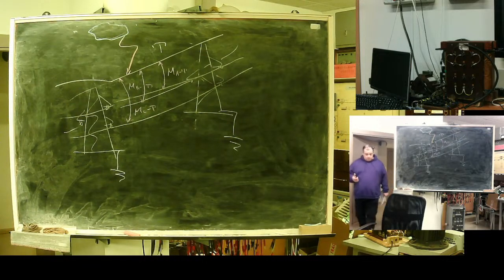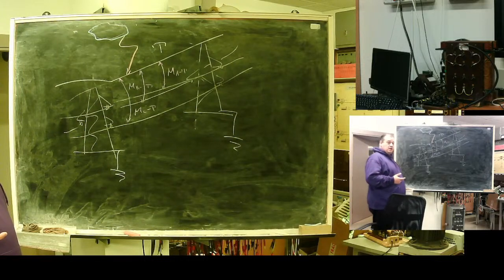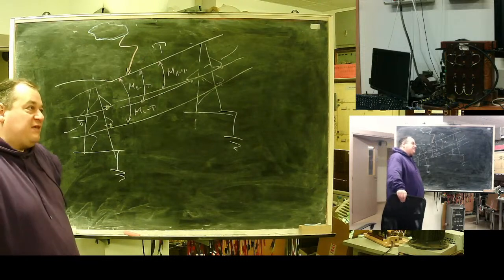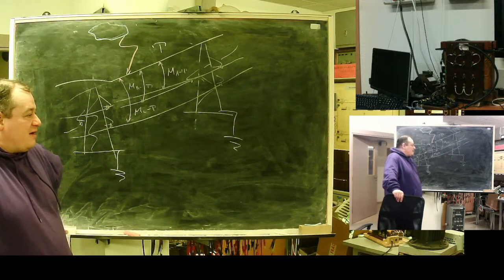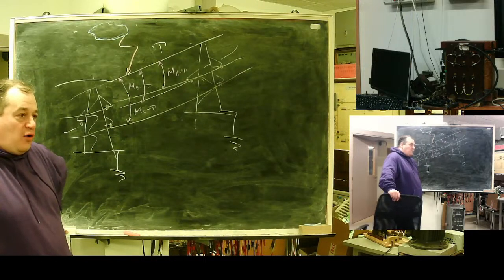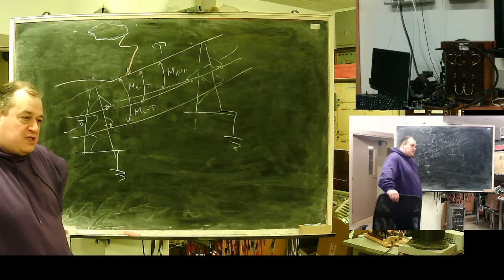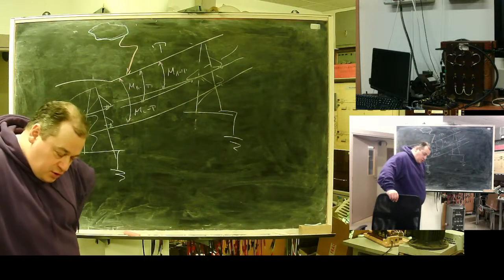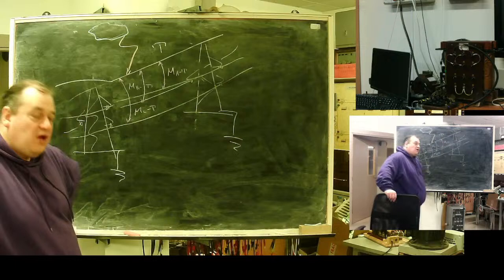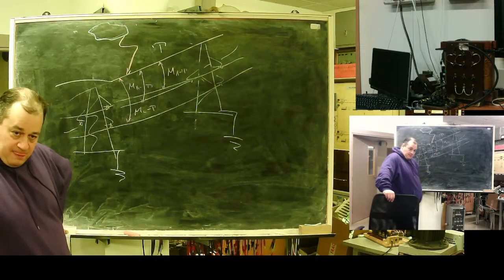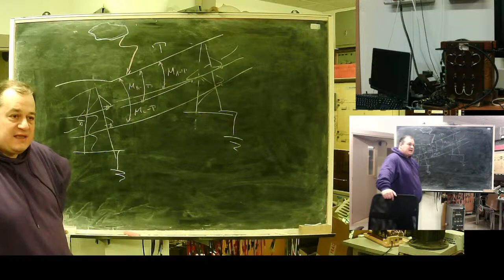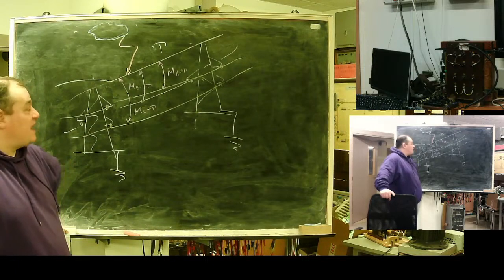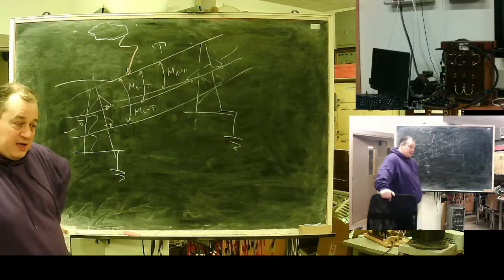Professor, actually, that cable, another name is ground wire, right? It's protective. Ground wire or protective wire is a bit different. Grounding is used to protect humans, animals, and so on from electric shock. It's a protective measure. This wire is grounded, but it's a lightning protection.